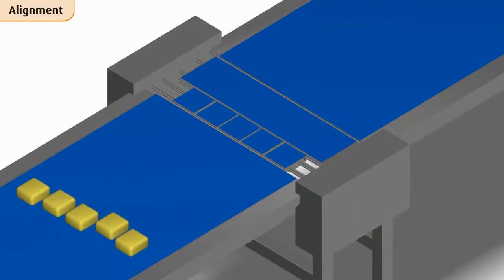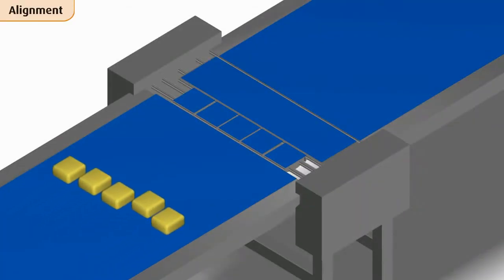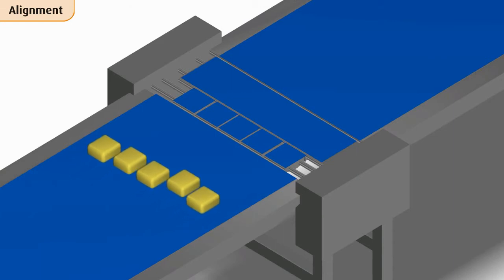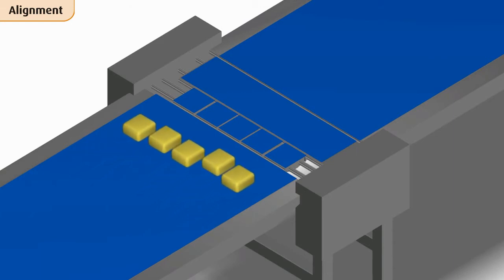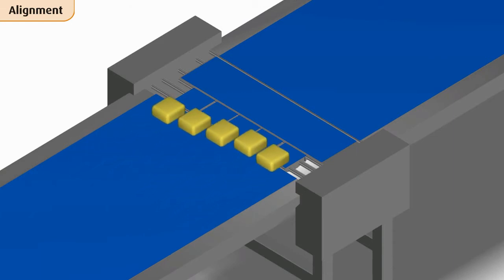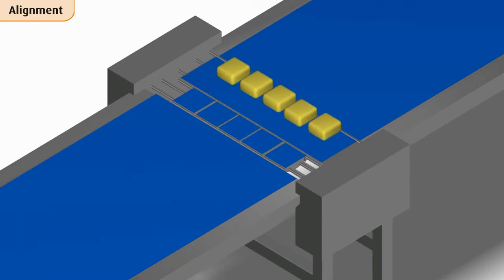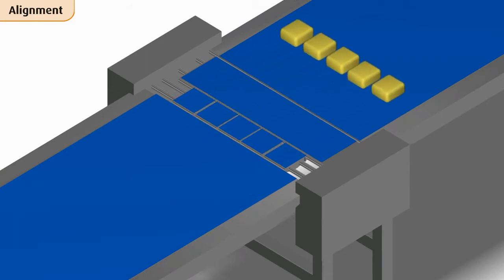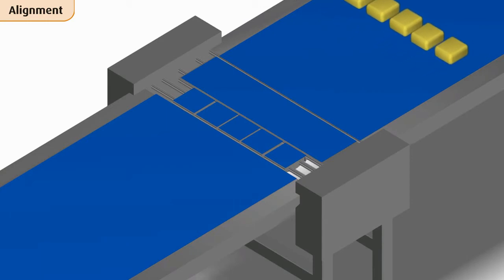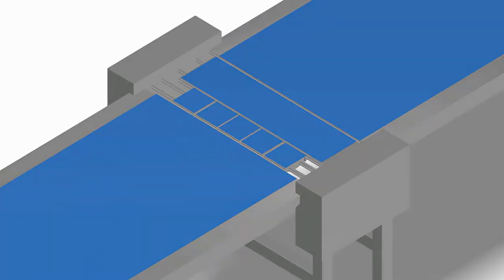It's possible that the dough pieces may be lying partly offline on the conveyor belt following portioning by the multi-blade guillotine or the Delta cutting robot. In order to achieve a correct delivery formation, we recommend using a downstream alignment belt, a module which aligns all the products back into their exact rows.